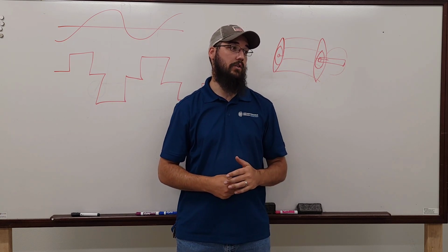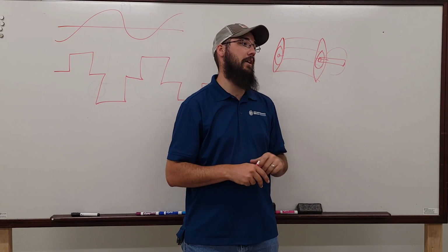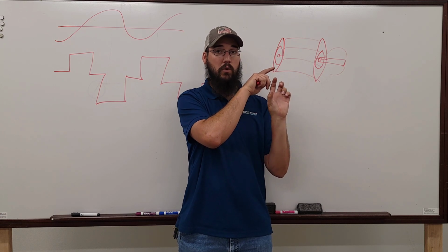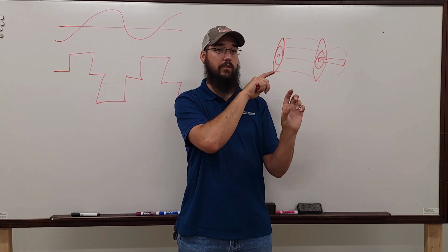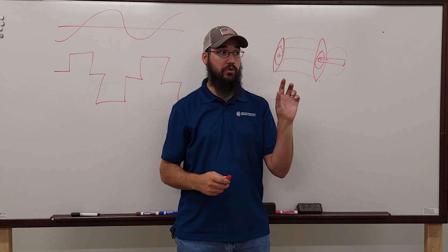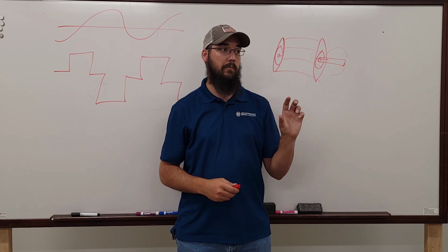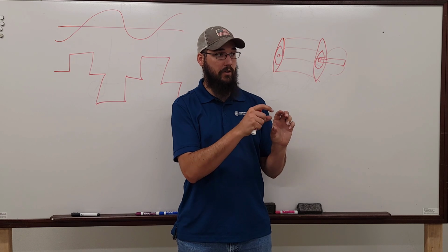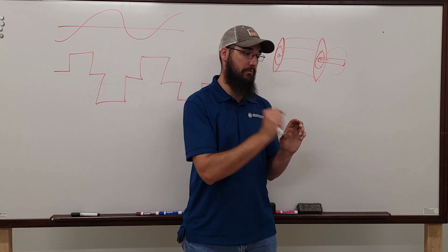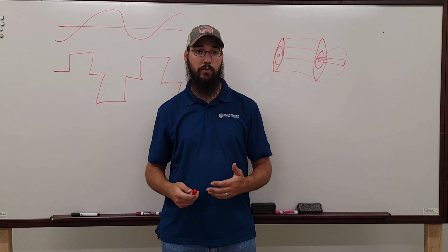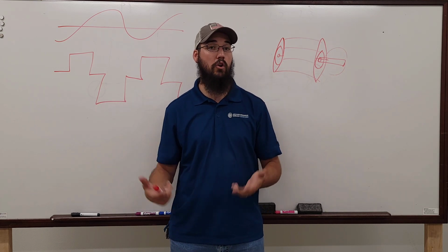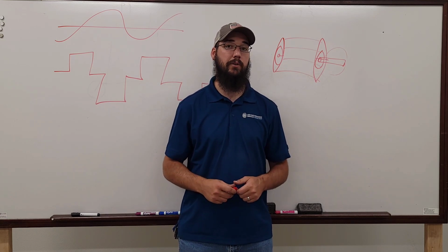Okay. Yeah. And so all that, it comes prefab that way. And then it's got a push spring behind it. And all it needs to do is just make one point of contact. That's all it's got to do. Now, one of the things to keep in mind is that the spring and those ground rings do wear out. They can get to where the spring or the ground pin will begin to stick, and it won't properly apply pressure against the shaft the way it needs to in order to just do its job. So those are our little things we have to pay attention to, because if we don't catch those things, we're going to fail a motor.